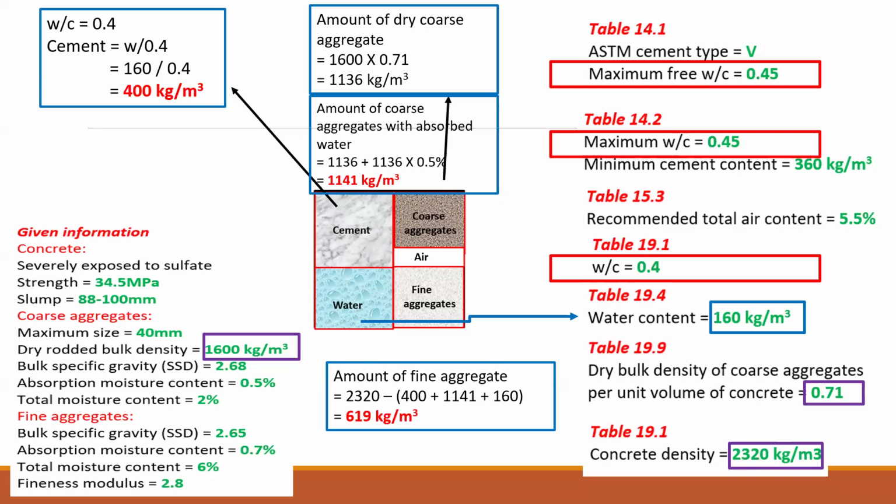concrete together, normally it is with air. So we don't want to have lumps of air here and there in the concrete. To get rid of that, we vibrate or we compact it, isn't it? So that is to get rid of the accidental air. But in air entrained concrete, the air is evenly distributed throughout the concrete because we are purposely doing it. We follow the process to do it using an admixture which forms the air. So that we don't consider for the weight here. However, any question?